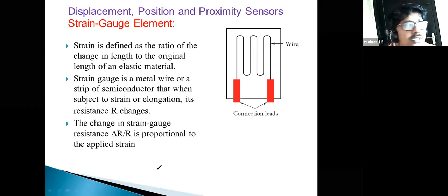You already did an experiment in the instrumentation control systems lab, right? The load measurement device. Here you add weights, and the display board shows the output. Sometimes it shows 900 grams, maybe 1.1, which means a small error is there. Inside it, there is a Wheatstone bridge, in the force or load measurement device.